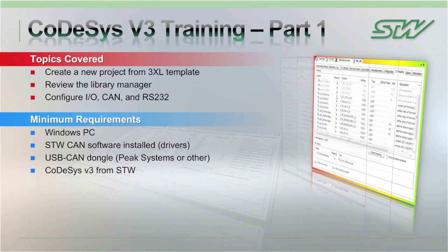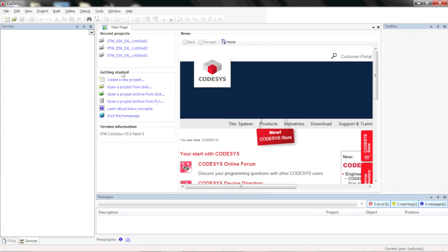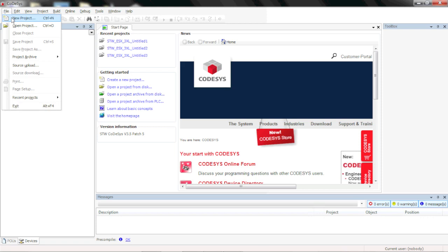So in this first video we're going to cover just opening CoDeSys, creating a project, and configuring some of the most common and most often used options and configurations for our project. So we'll start off here. You can either create a new project here, or we'll do File, New up here, it doesn't matter.